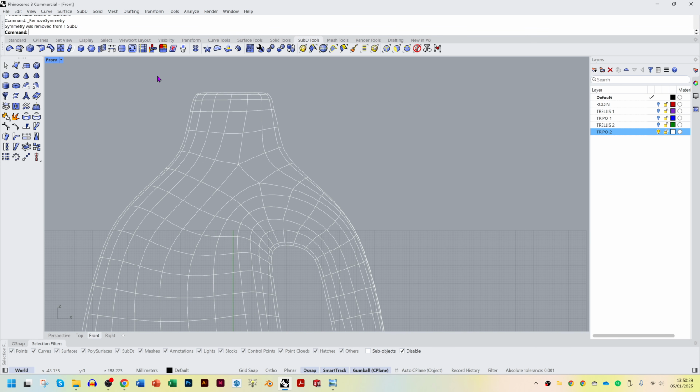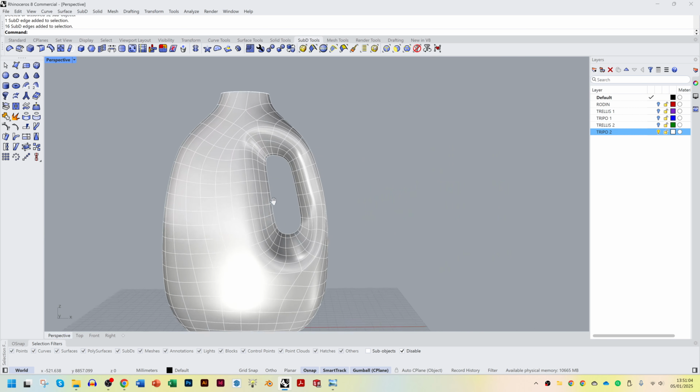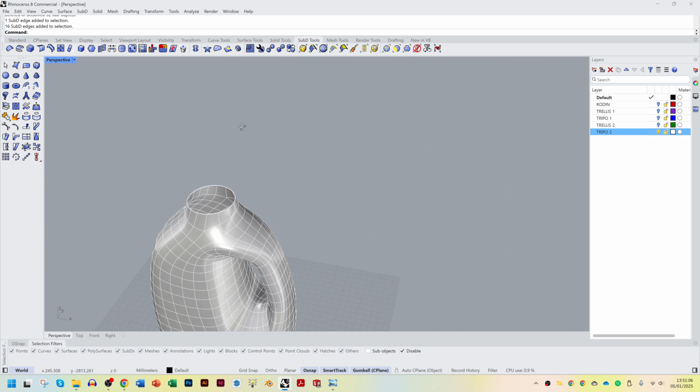Now, I wouldn't try and keep this as SubD here in this case. I'm just deciding where the lid is and where we would go into NURBS properly. So I think I'll take out all of that, and I think I would take out this as well. I think what I would do here is scale all of this to 0. If I go into my perspective view here, now I've got this kind of circular lid here, and from there I can just taper it up after.